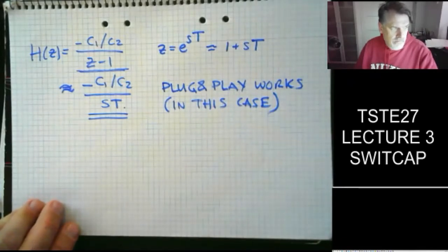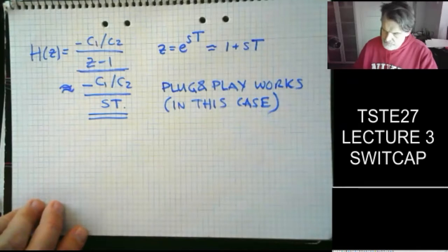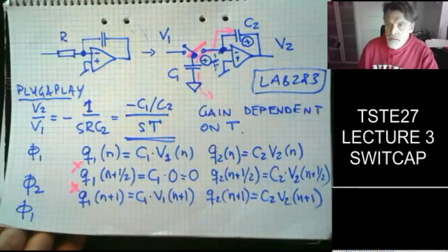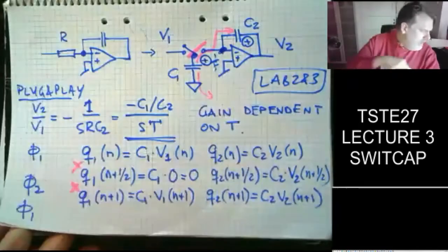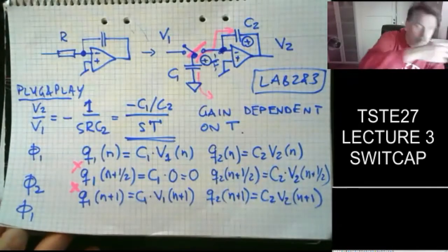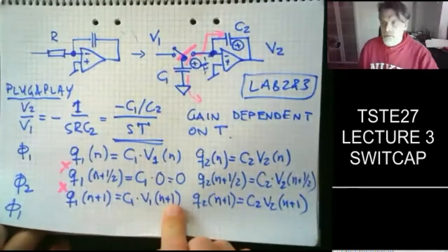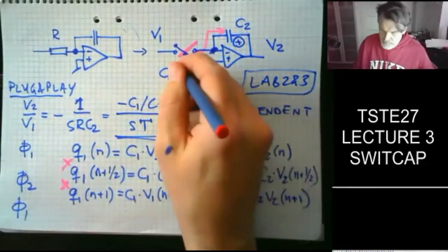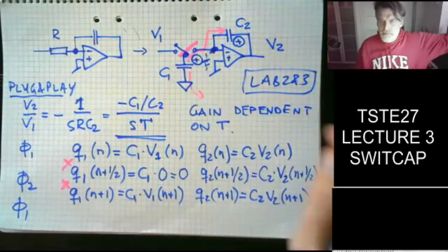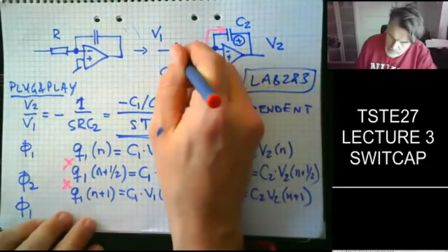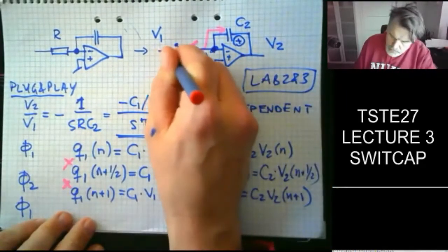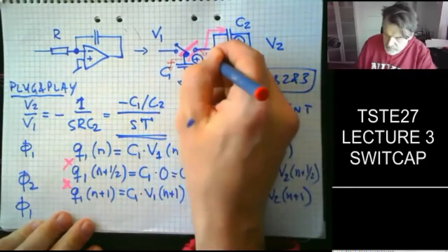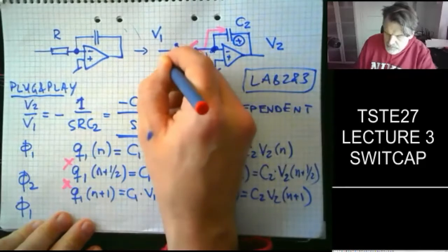We will have to modify this circuit a bit because it is sensitive to some extent. It's sensitive in the sense that once you want to implement this circuit, it's going to be sensitive towards additional capacitance associated, for example, with switches and op-amp inputs, and a lot of parasitics happening between the different places here.